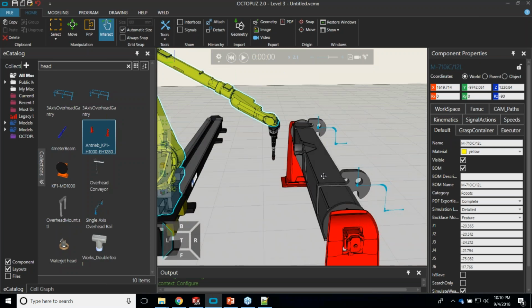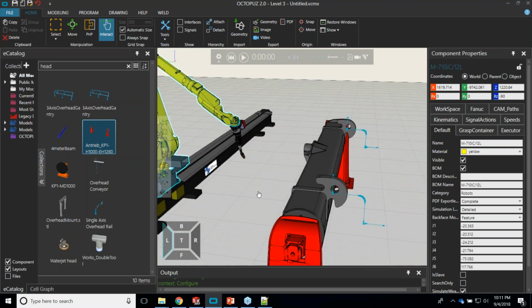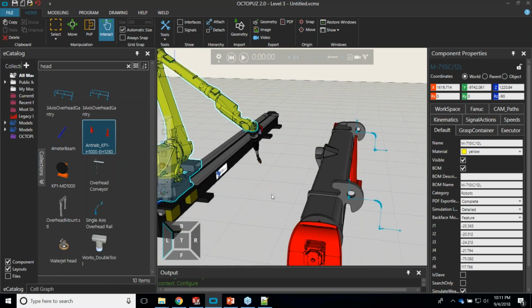And the closer you can get to that point, the lower your accuracy is going to be. And once you define that TCP with at least a 0.6 accuracy, or 0.6 error, that means that anything you program your robot to do in the future with that TCP, if you take that program and you want to repeat it over and over and over again, it's going to do that within a margin of error of 0.6 millimeters. That's the way that works.